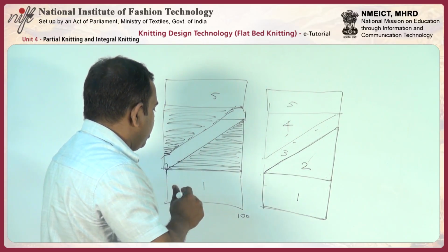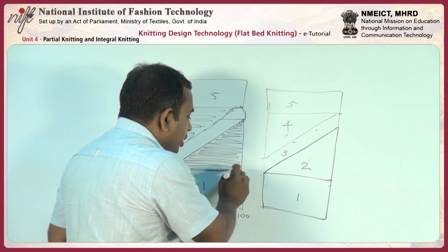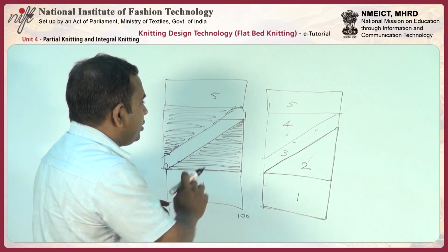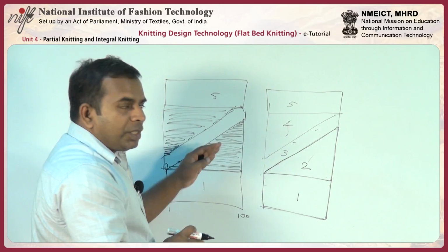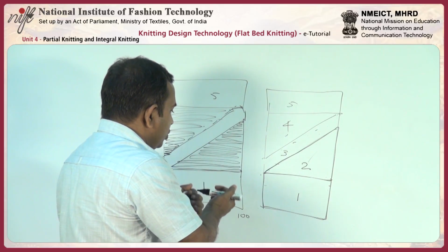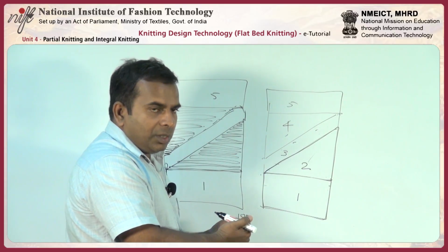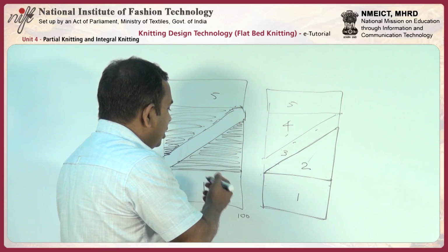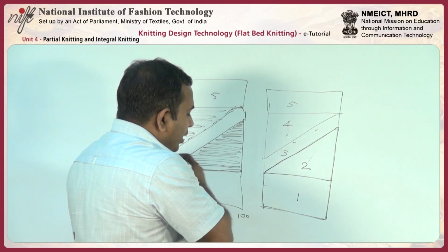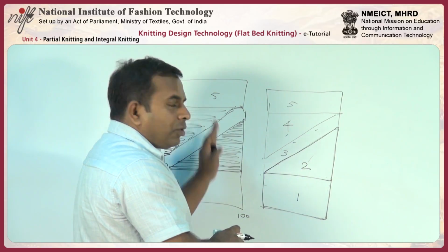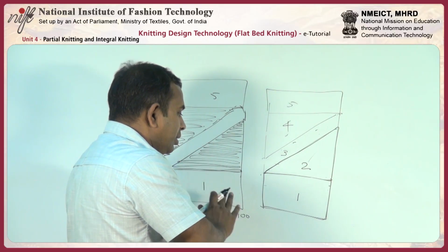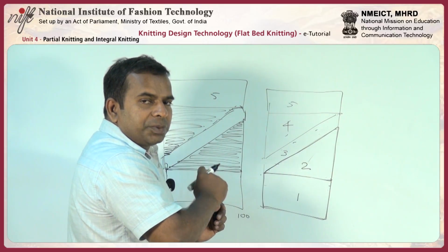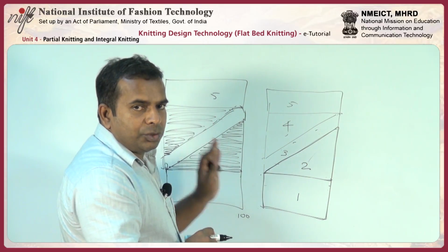What we mean by partial knitting is, we are not knitting fully, we are knitting only partially. The challenge of partial knitting is, to perform knitting, you all know, we need to hold the loops down. To hold the loops down, we need to apply force. When we apply force while knitting, the needles go up and the loops are retained in the same space wherever they were, and that's the reason the loops clear the needle latch and go up and catch the new thread.